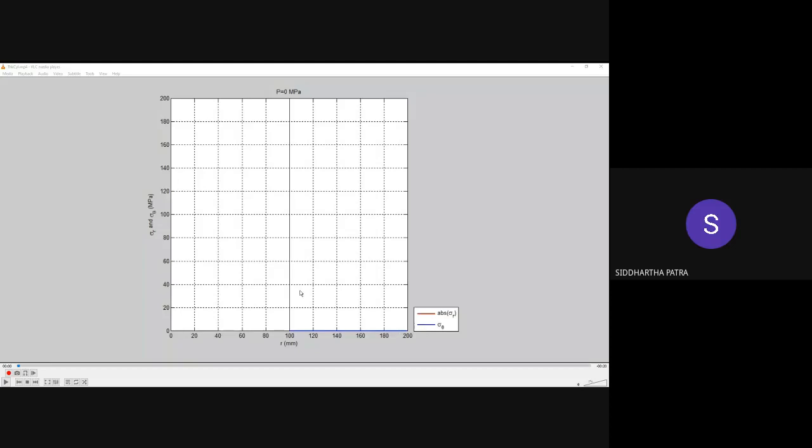And in elastic deformation, you would expect the sum of the radial stress and the tangential stress to be the same. But because I took the absolute value of sigma r, you would see that the difference between the two lines remains the same across the radius. It's not with changing pressure that the difference remains the same; it's along the radius for a given pressure.